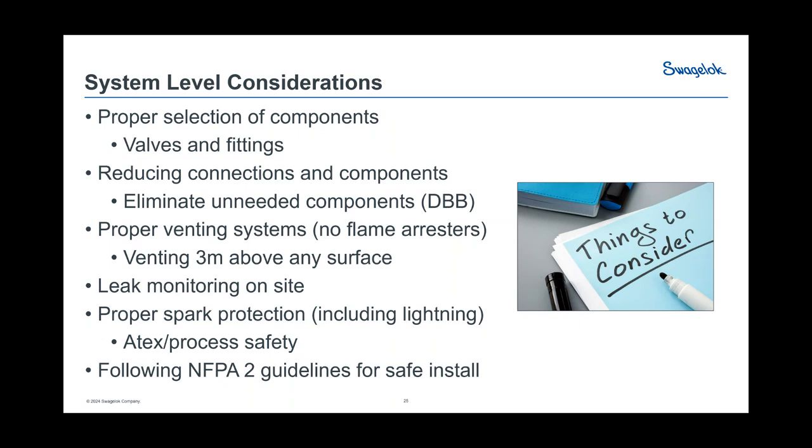So while hydrogen, when it comes in contact with oxygen, can create a flame, there's designs for the venting being, for example, it needs to be 3 meters above any surface, or at least 10 feet off the ground. So if there was a flame in a vent system, it's not shooting in somebody's face or catching any surface on fire.